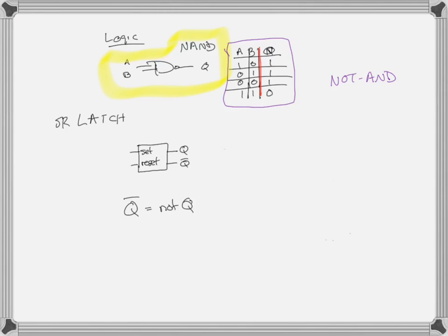And so now we've got sequential logic. Sequential logic depends both on what's on the inputs, but also on what was on the output after the last input. This particular latch, this particular piece of logic or memory bit, is called the SR latch because it's got a set and a reset input. As an output, it still has just the output, which is called Q.